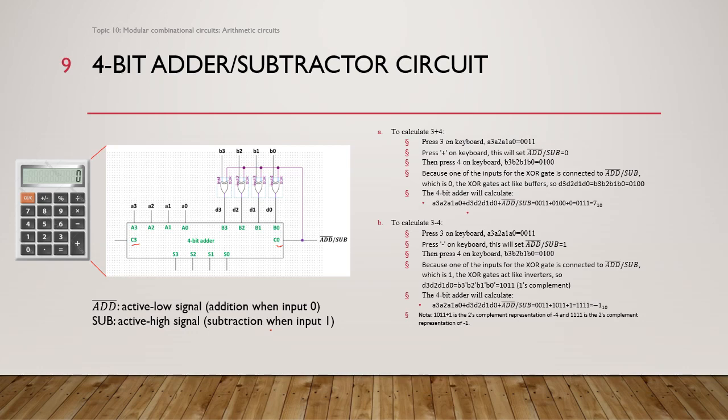Okay, and one more thing about this input here: it is called ADD bar slash SUB. You will see this type of naming strategy throughout this chapter, when talking about the modular circuits. They named those signals this way because this can tell us some information about that input or output. It will tell us the active levels and the corresponding functions.